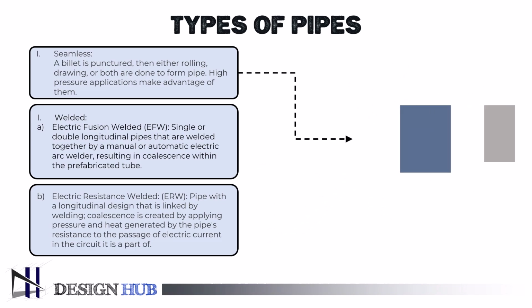They are created by using a mandrel to extrude a solid, almost molten steel rod known as a billet into a hollow form. Firstly, they heat the billet. Then shape the billet into a circular, oblong mold that is pierced and hollowed out. Then extend the mold by drawing it through a mandrel rod while it's still hot. Utilizing cold rolling, cold drawing, or pilgering, give the tubing more shape.